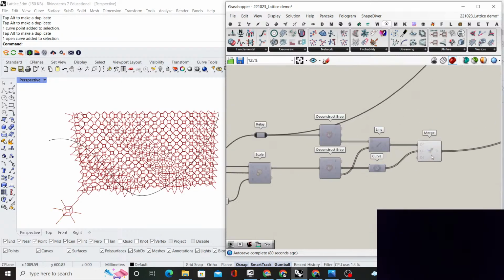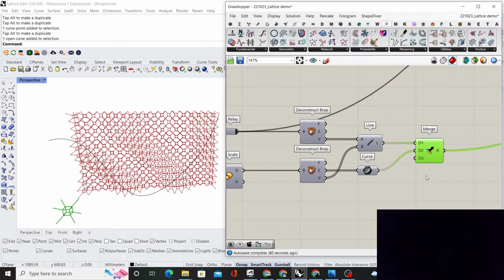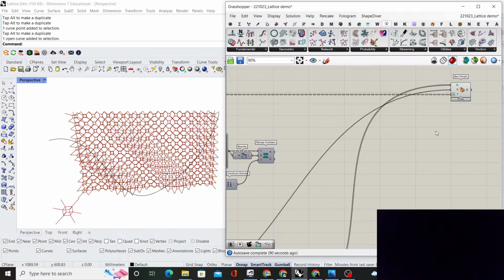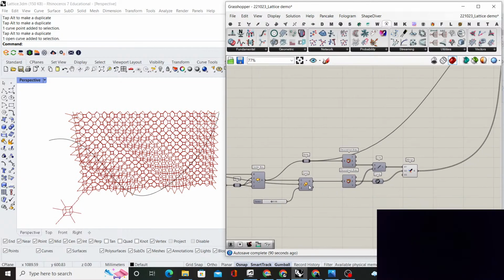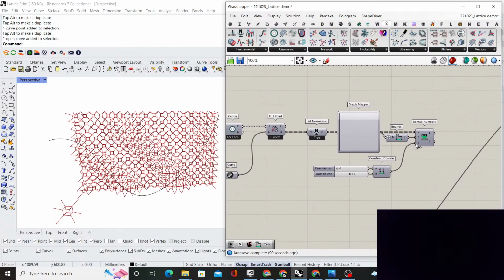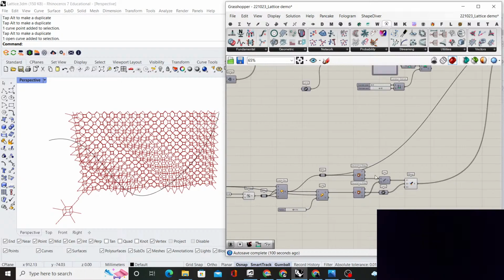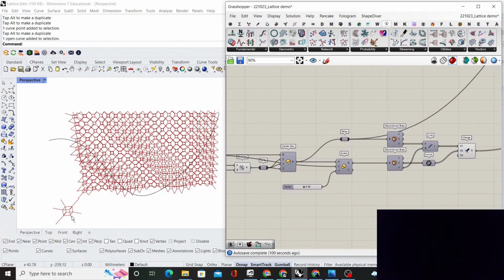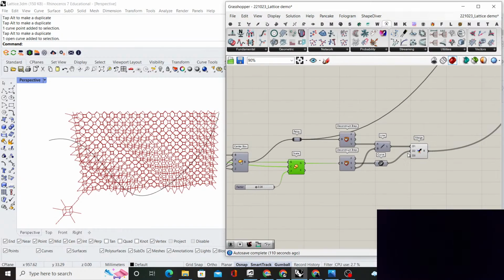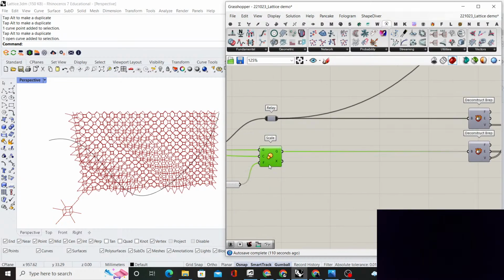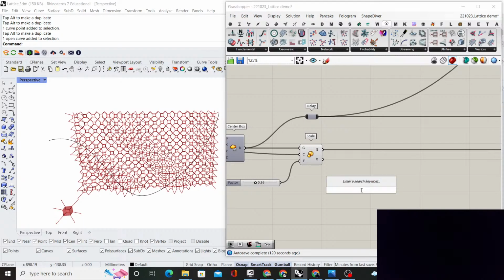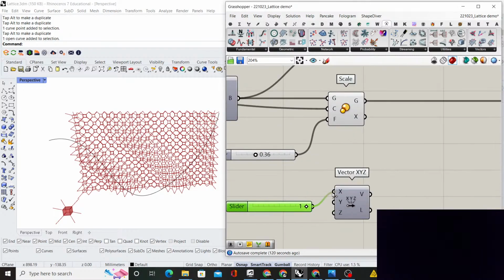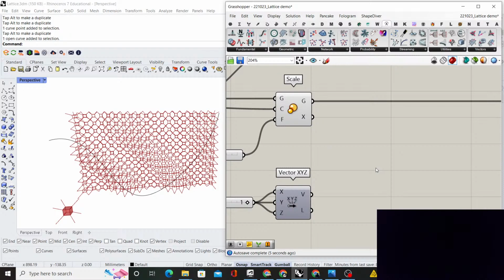So let's take it from here, and let's place it into the boxes. We have these points, we have these distances, and now we just need to create as many of these boxes as we have here, right? First of all, I'm gonna create the axis against which we'll rotate this box. So I'm gonna start from here. I'm gonna take this box. For the axis, I'm gonna just use an x, y, z vector, and each of these parameters is gonna be set to 1, which will give us an axis which goes at 45 degrees to our box in all planes.